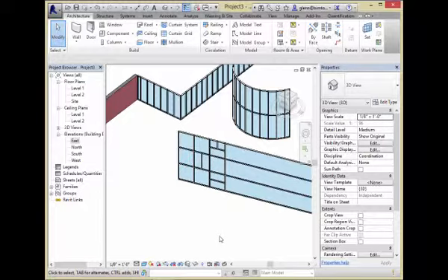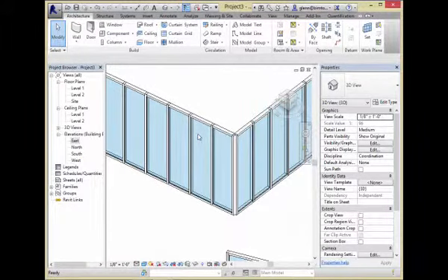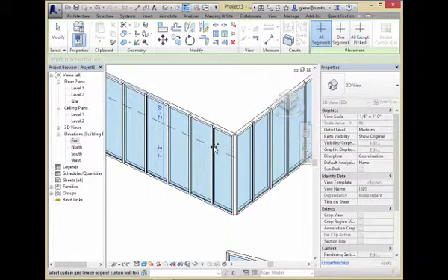And I'm just going to start making some changes to that. Maybe I'll put something at the bottom and break it off in a different material, or do some sort of alternating pattern to it. I might start with a pattern-based curtain wall, then enhance it. Here's how you do that. I'll zoom in there. Even though I'm looking at that pattern-based wall, I can use the curtain grid tool to add things to it. So I can break it up a little further.